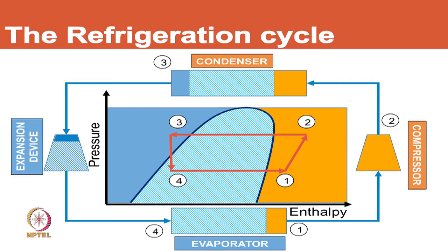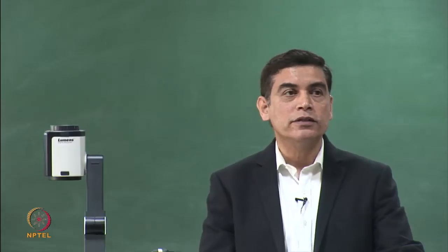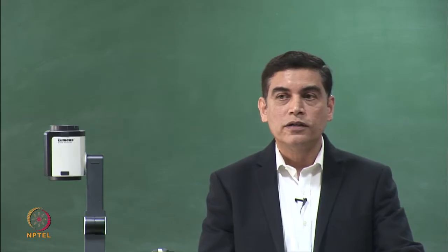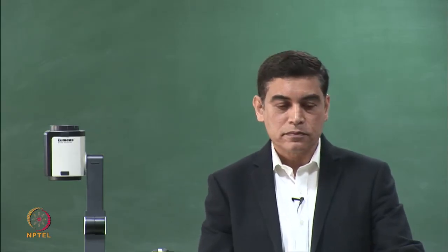If you look at this diagram, you can see some zones. There is a light yellow zone which implies this is all superheated vapor. Then we have a zone inside this region which is a two-phase zone, a combination of liquid and vapor. This is where condensation and evaporation take place, and this is actually the sweet spot. The closest we can get to a Carnot cycle for transfer of heat at the condensing temperature and the evaporating temperature is inside this zone of two phases coexisting.